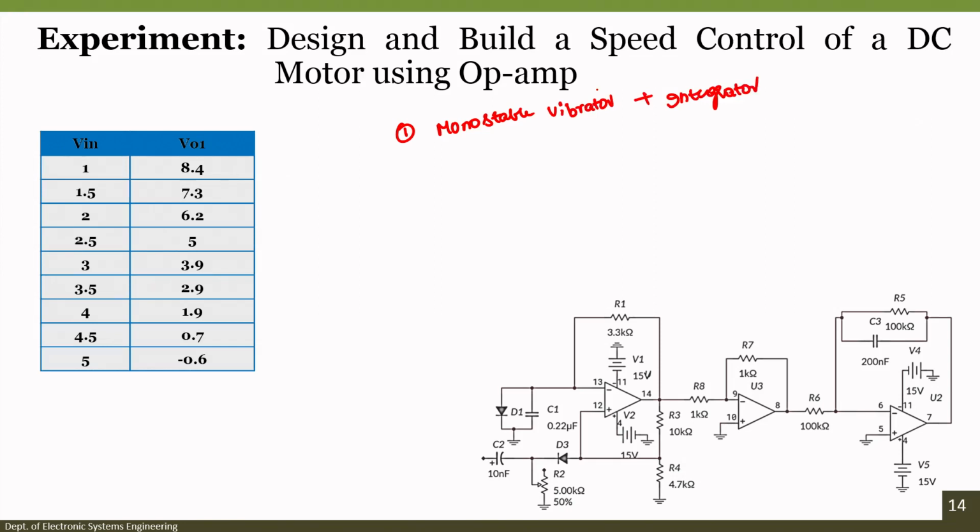The reason is that, based upon the change in RPM, the frequency of the signal keeps on varying. Moreover, since it is based upon the number of pulses, when you look into the working of our encoder, it depends on how much time the toothed wheel is in contact with respect to the Hall effect sensor.